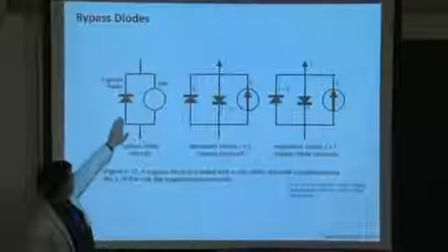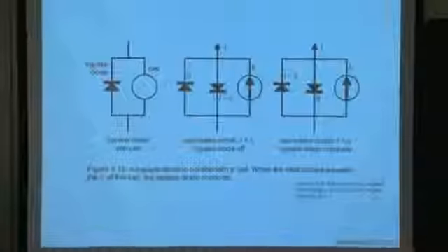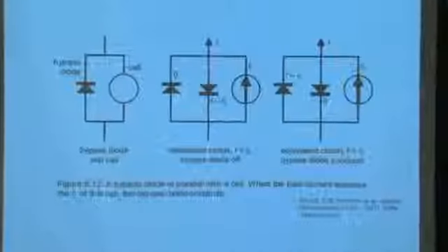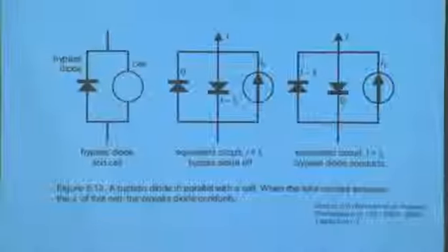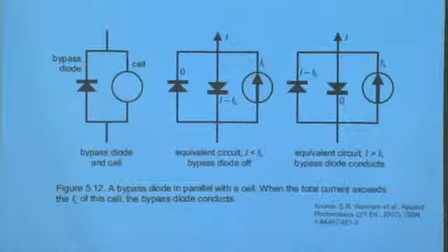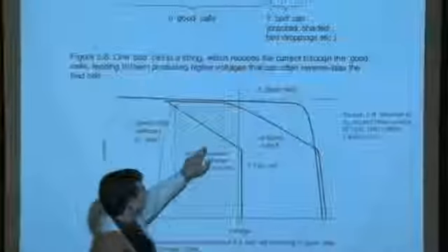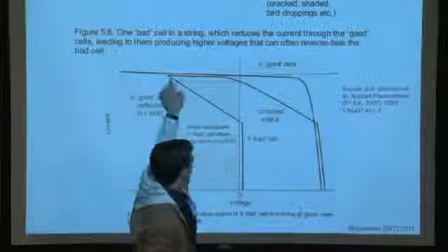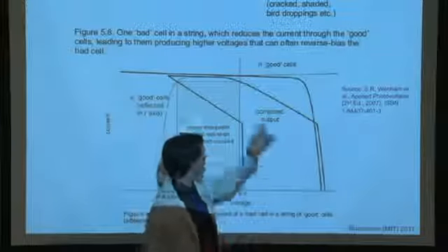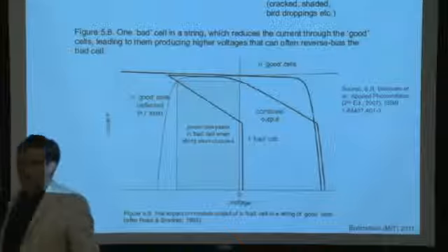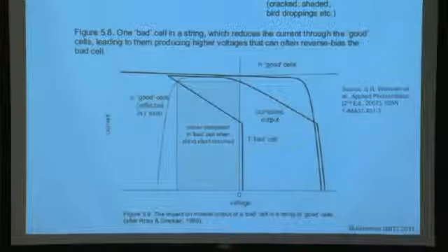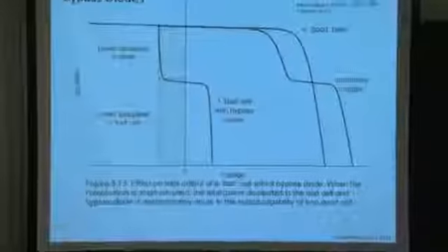The simple principle of a bypass diode of a cell is this. If the reverse bias current becomes too large, instead of forcing the current to flow through the bad cell, you can force it to flow around it through a bypass diode. And therefore, it short circuits, it leaves the cell out of the circuit, right? The current is flowing around it. And so you result in less of a degradation of your module. To put it from an equivalent IV curve perspective, instead of adding this IV curve here with the rest of them, you're simply moving the current around it, so you'd have the n good cells, and that's it, end of story. The 10th cell would just be taken out of your circuit. It would be pushed aside. OK, so on a cell level, that makes sense.